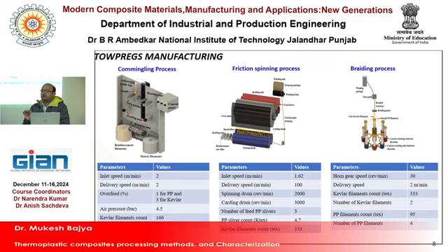You want to make aramid and polypropylene composites. Aramid fibers are basically used for high modulus and high strength, and the polypropylene will act as a resin material. That will bind all the aramid fibers, or you can say preforms, together, and then you can make the composites.